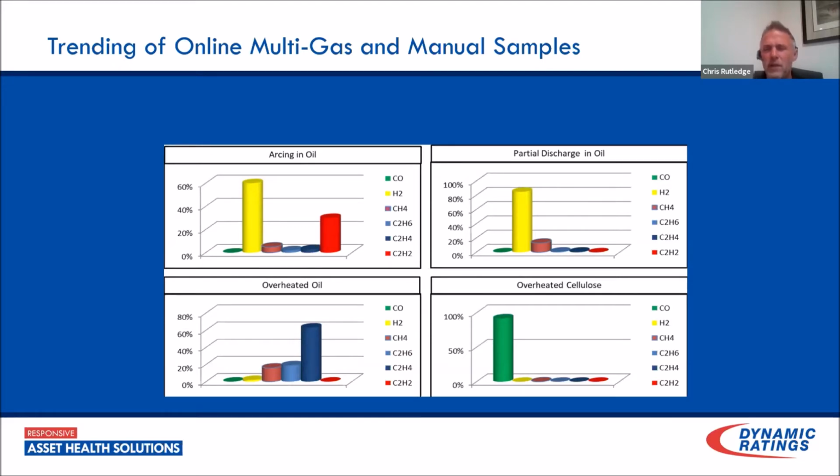We're going to go into the ratio between carbon monoxide and carbon dioxide a bit. I feel like this can be a little bit misleading, as CO quickly migrates to headspace and quickly gets out of any leaks you have on that transformer. So we're going to look at some incidences where CO values haven't changed a lot, but the ratio between the two gases, CO and CO2, has changed, and we were starting to see the beginnings of failure of the solid insulation system of that transformer.